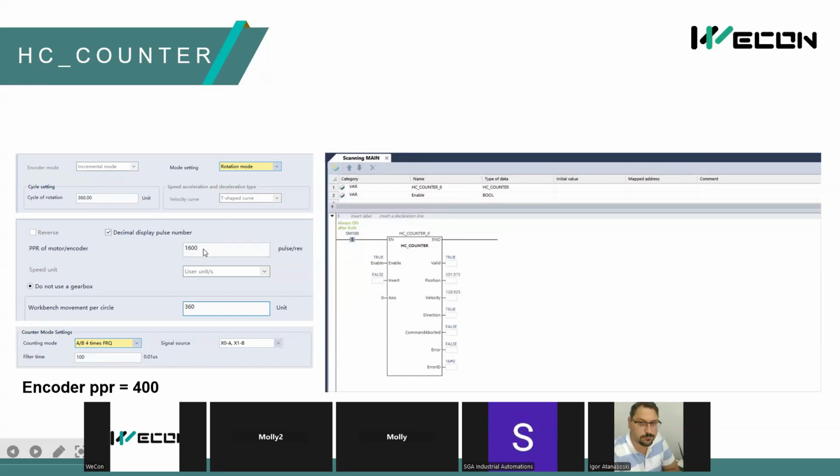So here, when the encoder rotates one round, our PLC will receive 1,600 pulses. That's why I put this value here. And also I set the user unit as 360. So it means when the encoder rotates one round, our counting value will increase by 360.